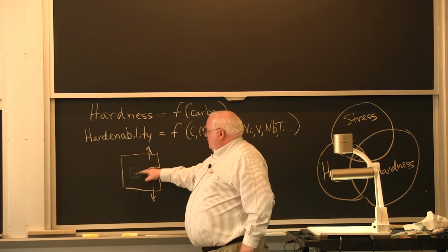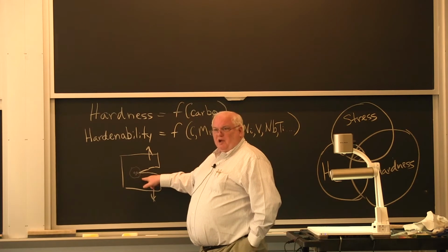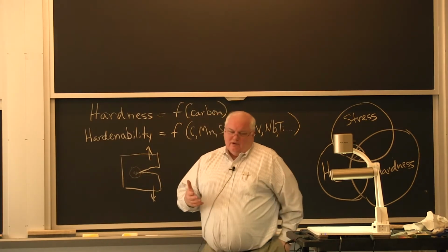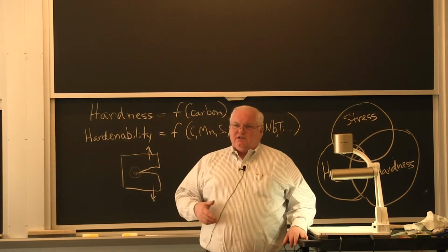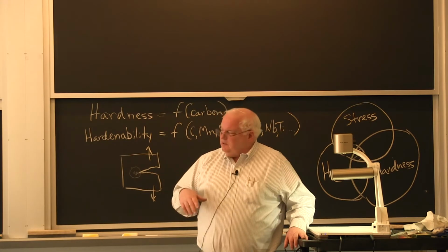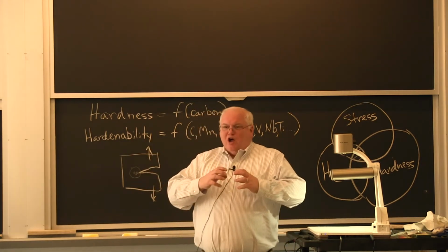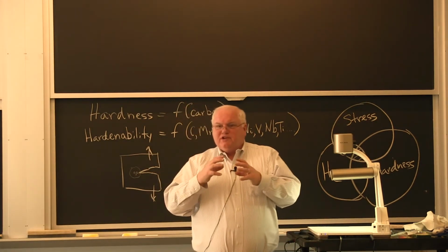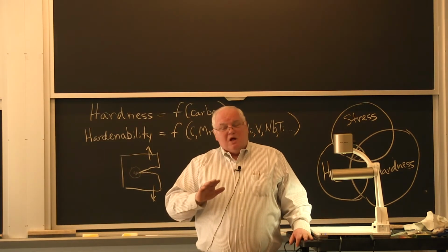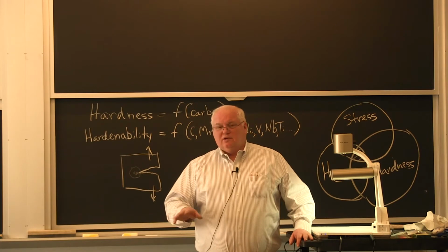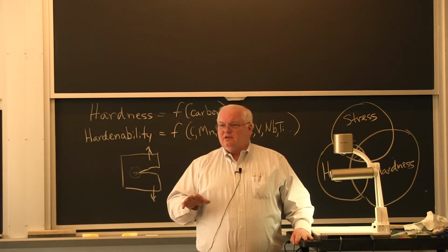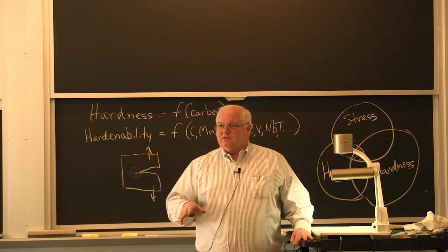The hydrogen diffused to the crack tip during those 8 hours. Now, what to do? They had to keep building some of these things, so they used austenitic stainless steel. Austenitic stainless steel has a face-centered cubic structure. There's lots of room for the hydrogen in a face-centered cubic structure as opposed to a body-centered cubic structure. The cracking susceptibility of austenitic stainless steels is much, much less than body-centered cubic steels.